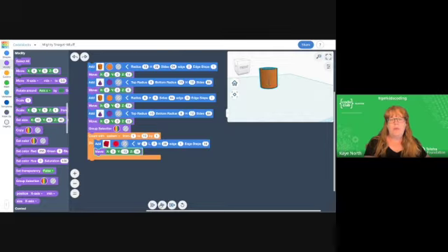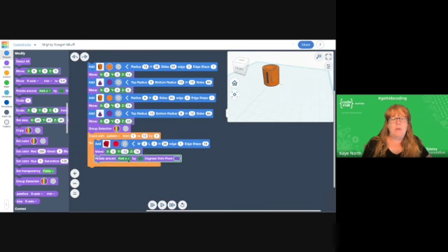Now, if you were to run that program now and watch it take place, we're going to see that hole start to build there, which is great. That's exactly what we want. But all of them have fit into the same place. We want that repeating pattern to go around the outside. To do this, we're going to rotate around the Z axis.